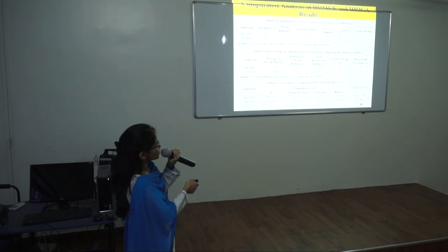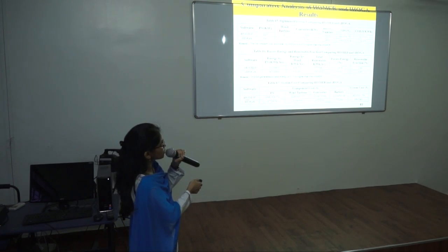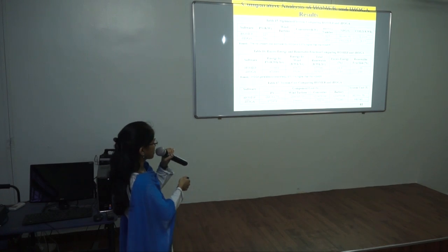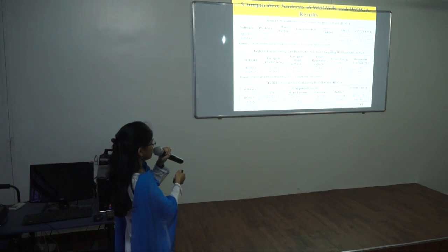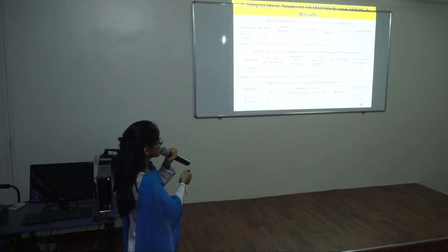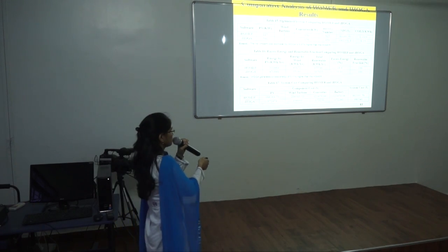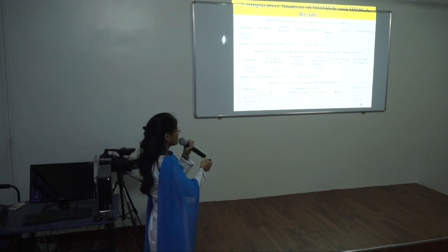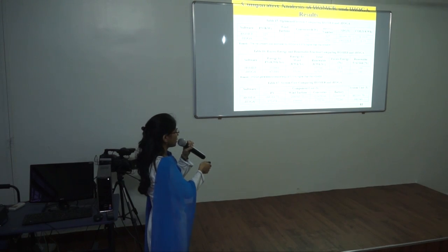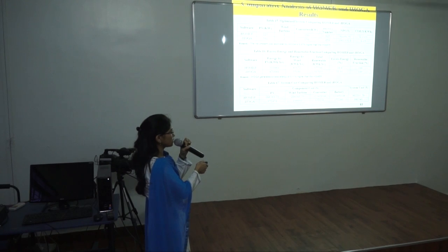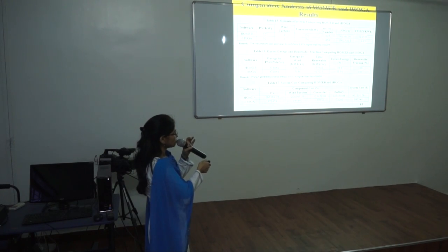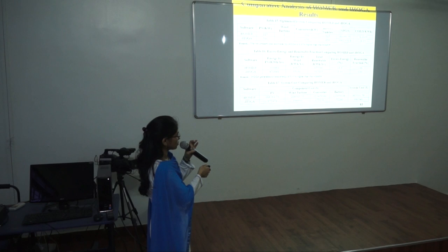$903,391.70 with cost of energy equal to $0.1323 per kilowatt hour. On the other hand, IHOGA predicts the system which consists of 501 kilowatt of PV panels with 2 wind turbines of 50 kilowatt each, a converter of 150 kilowatt and 450 batteries, of which 25 are in series and 14 are in parallel, which produces the minimum net present cost of 1,002,330.9.